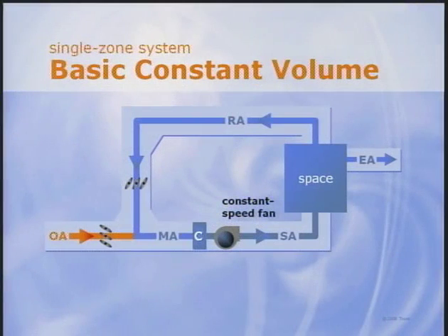Depending upon building design and climate conditions, some systems can meet this requirement without direct humidity control. Other systems can't. Let's look at a few systems analyzed as required by Standard 62. Perhaps most common, the single-zone constant volume system supplies a constant quantity of mixed air to a single zone at a temperature that depends on sensible load.